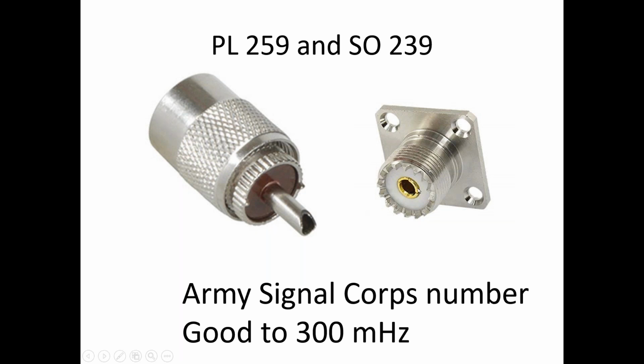This bump out actually changes the distance between the inner conductor and the outer conductor. So for your information, a PL259, which we rate at 50 ohms, is actually, now what do we say? If you increase the distance, it's going to be less characteristic impedance.